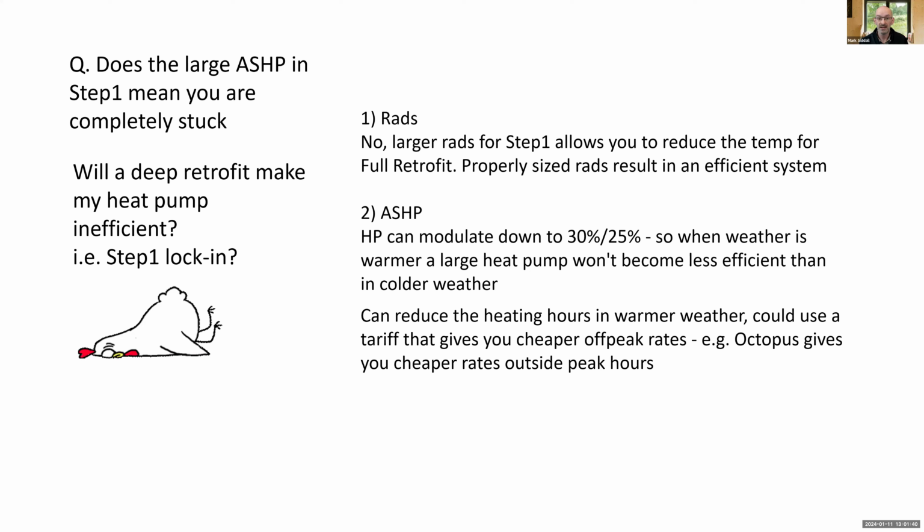If you've got an older property, then dare I say, if it's got solid wall construction and wet plaster walls, it's going to be easier to achieve the air tightness target than if you've got a 1980s dot and dab plasterboarded property. So all of these things need to be considered, and that's why having the right professionals on board to help guide you through the process and understand the systems of where we stand and how to deal with things.